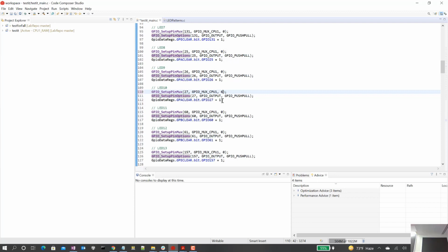And again, where to use that, I usually find that in TI examples, and you'll see that. You'll see even in this week's lab, they recommend that we disable the pull-up resistor when we set up a pin as PWM. Okay? All right. Good.